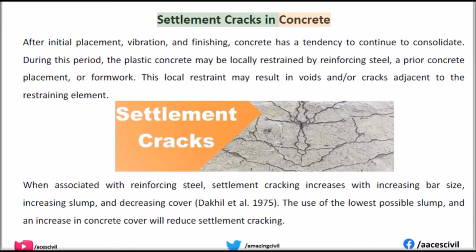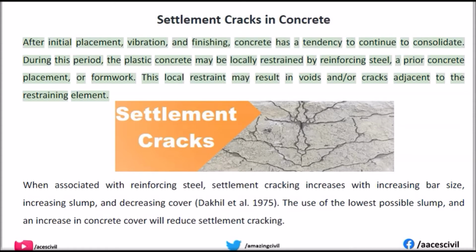Settlement cracks in concrete. After initial placement, vibration, and finishing, concrete has a tendency to continue to consolidate. During this period, the plastic concrete may be locally restrained by reinforcing steel, a prior concrete placement, or formwork. This local restraint may result in voids and/or cracks adjacent to the restraining element.